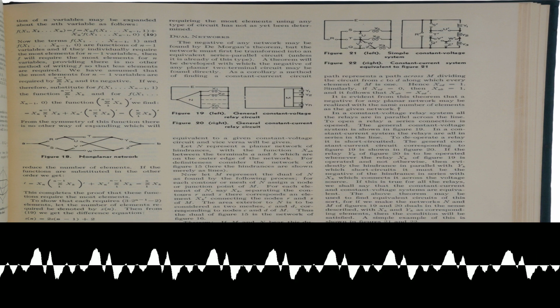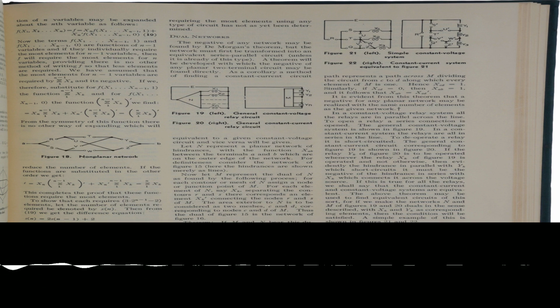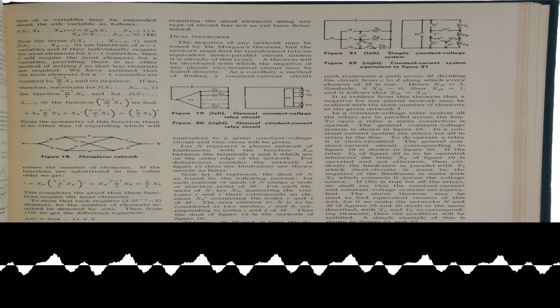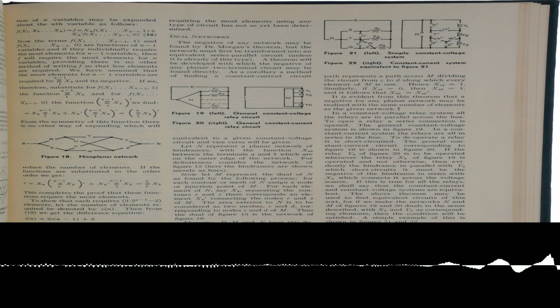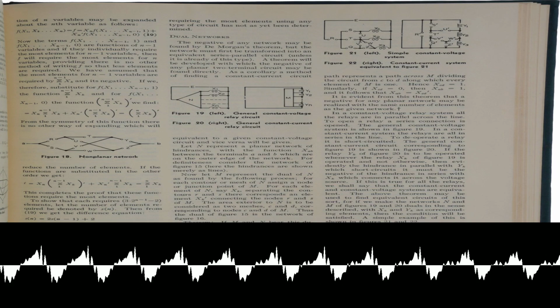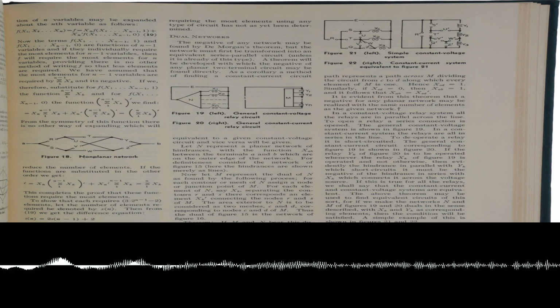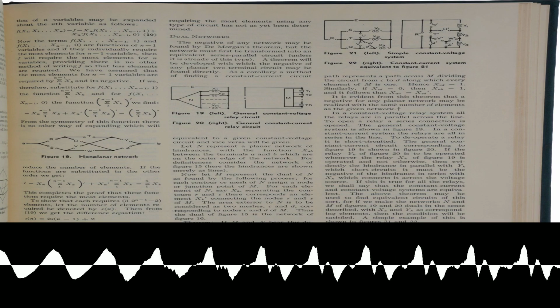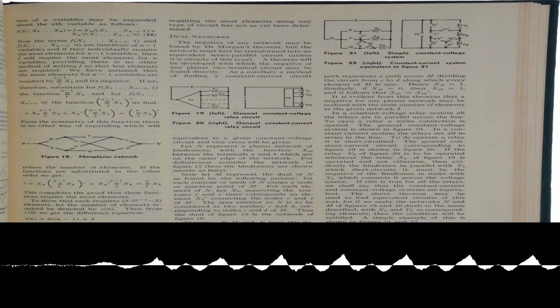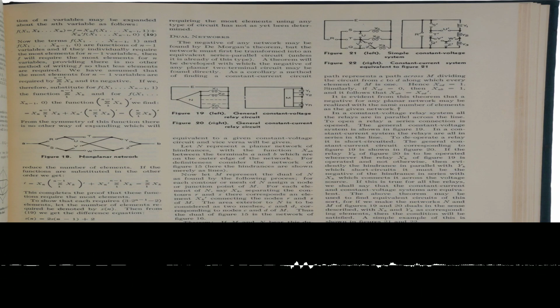He provides examples to demonstrate minimization techniques, removing redundant switches or connections. By applying Boolean identities, he explains how the use of the algebra directly leads to optimization of the circuit, saving cost and increasing reliability. Critically, he acknowledges that algebraic simplicity does not invariably correlate to physical simplicity.